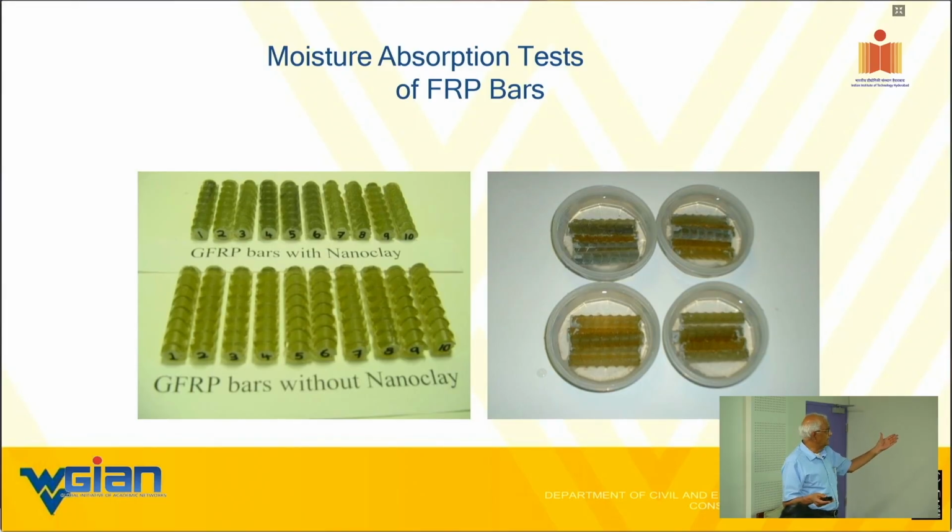You can see very systematically, we did some with nanoclay, without nanoclay. That clay is montmorillonite clay. We have certain exfoliation problems when we mix with it, so you need to have a special mixture and all that. Otherwise you're going to get into intercalation issues.